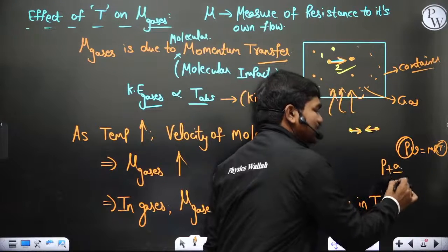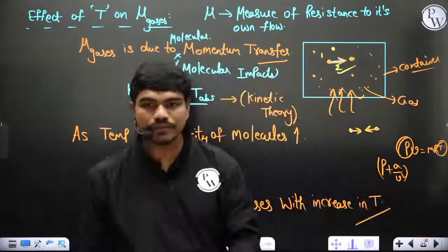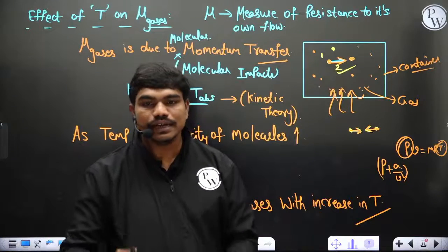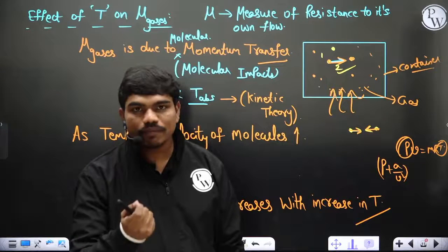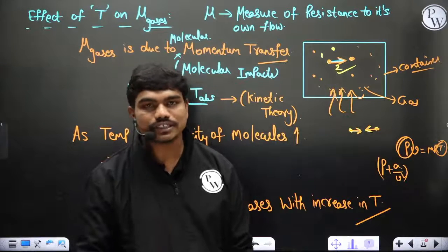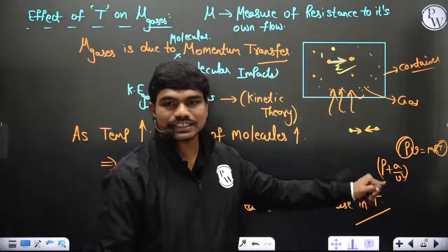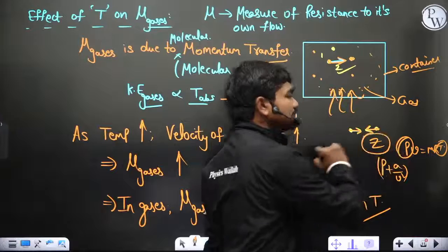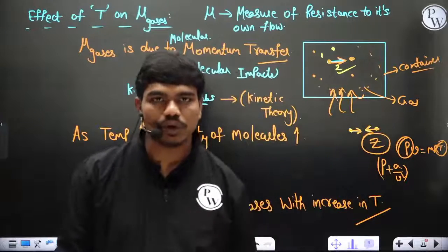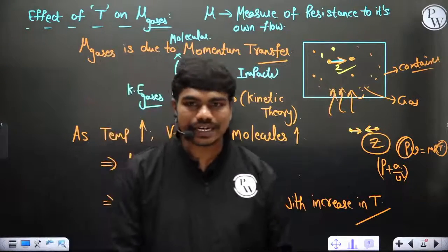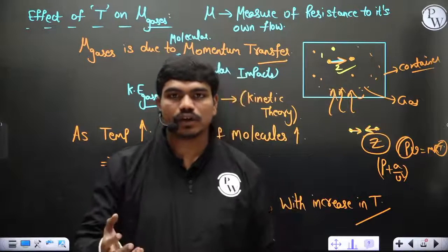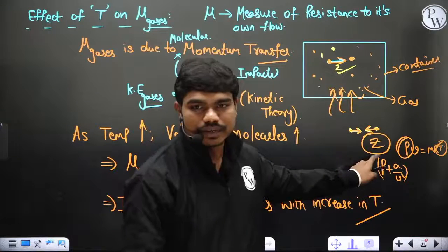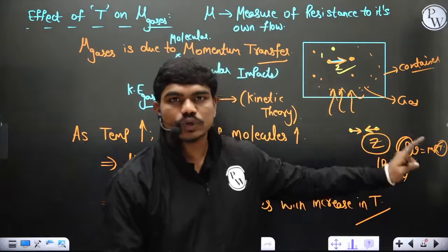If it is not an ideal gas, you also have equations like van der Waals and Berthelot's equations. You have a lot of different stuff where the effect of pressure can also be converted in terms of effect of temperature in general. In liquids the effect of pressure is generally very small because practically liquids are incompressible, but in case of gases pressure does have a significant effect that depends on something called the compressibility factor Z. That again moves to thermodynamics. You all know compressibility factor Z obviously. Z decides how a substance behaves when you apply pressure, and that depends on how a gas behaves. So that's why we again should go to thermodynamics for knowing that.